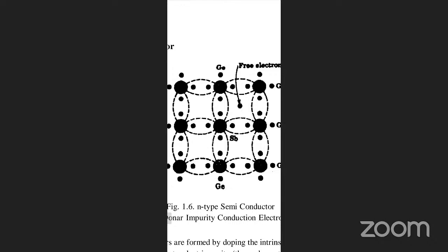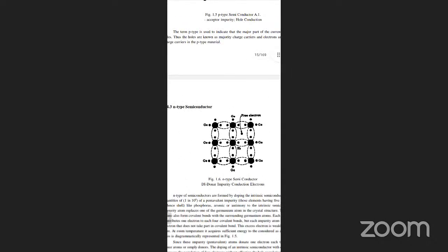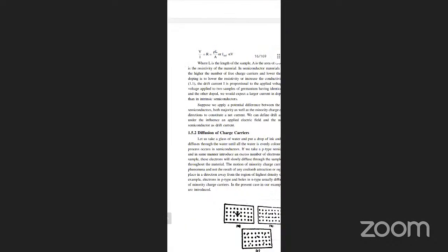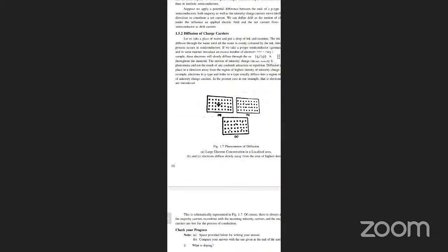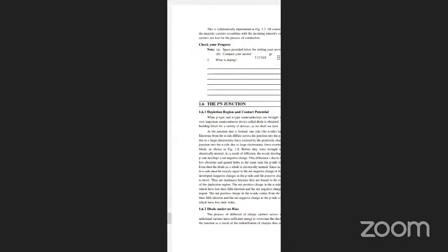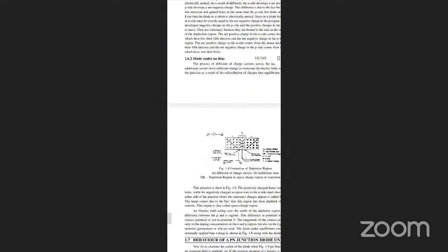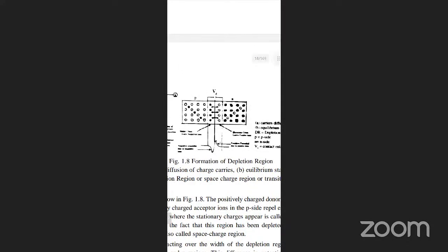Okay, next, what is a PN junction diode? Junction diode means that when a p-type semiconductor material is fused with the n-type semiconductor material, where p-type consists of majority positive holes and n-type consists of majority negative electrons, and both are fused with each other by using a specialized technique, a junction is formed. That means a junction which separates the two different regions. That's why this diode can be called a PN diode, a junction diode.